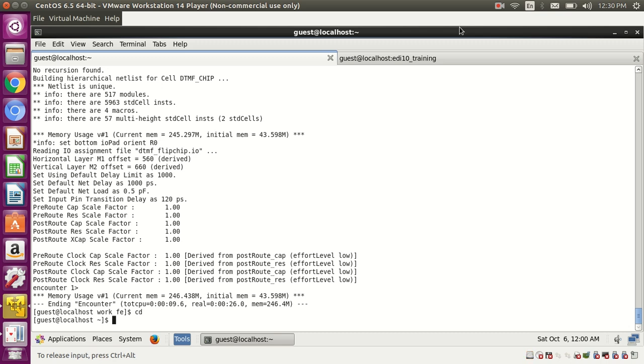First it will sort all the power nets. With power nets, the thing is that power or ground nets will not become aggressors and they will not become victims either. There is no SI concept with VDD or VSS, because they are always stable. So then it will see the clock nets, and after taking all the clock nets, it will see where they are and whether there are any parallel metal shapes.